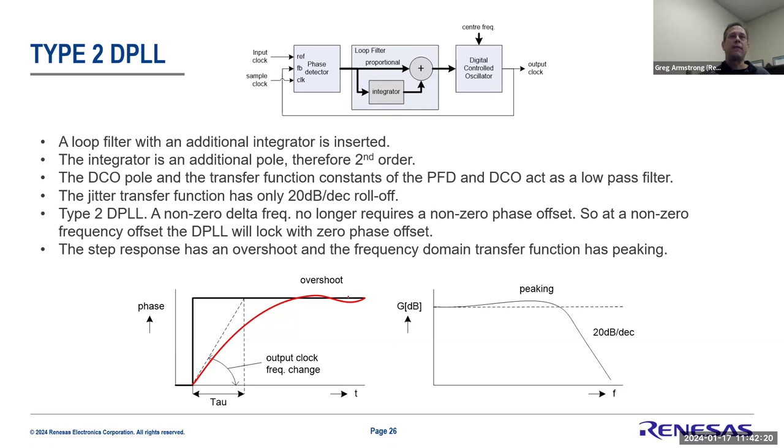But if you go down to a fundamental common frequency, they would have a common edge alignment traceability over time, like a 1 PPS or 8 kilohertz. But the other component they have to be aware of is one thing that the integrator allows us to do, is control how fast we react to changes of the clock.